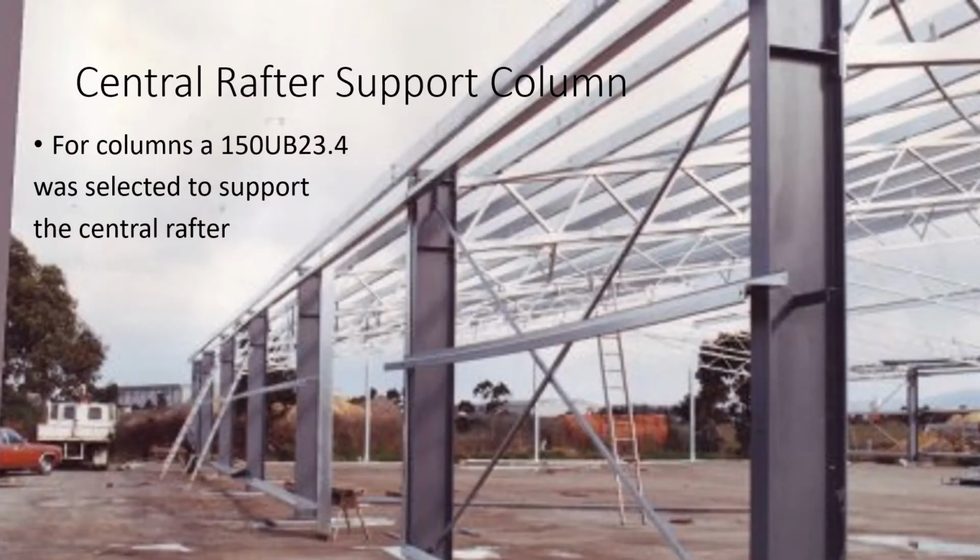For columns, a 150 UB 23.4 was selected to support the central rafter. These intermediate columns need to be larger than the end columns as they carry more load. For this selection, there aren't many similar alternatives on the capacity table, but the 150 UB 23.4 is still the best choice as it is strong enough whilst being the lightest. This reduces materials needed and also saves money on purchasing costs.